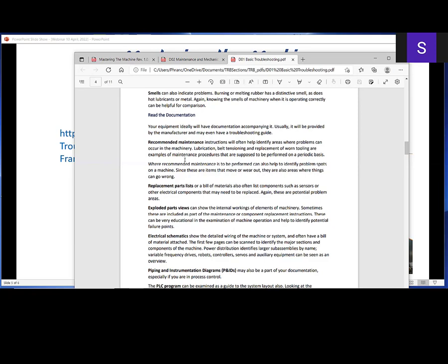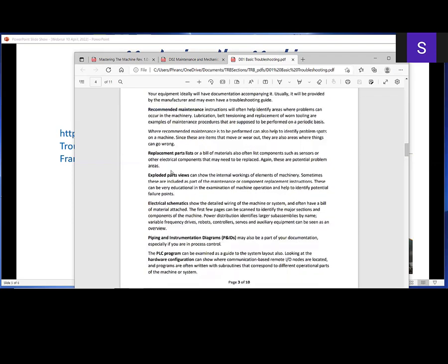Most of those quick disconnect cables are pretty standardized across the industry. So it doesn't matter, pin 1 is maybe positive, pin 3 is negative, and pin 4 is the signal. As long as that's true, it doesn't matter what brand of photo eye you use. So knowing your replacement parts list and identifying alternatives early is a pretty good thing to do.